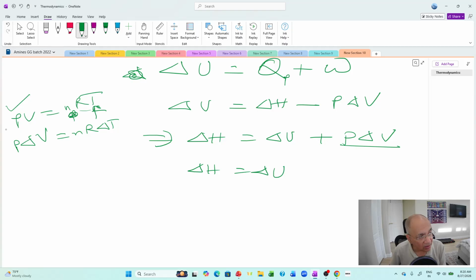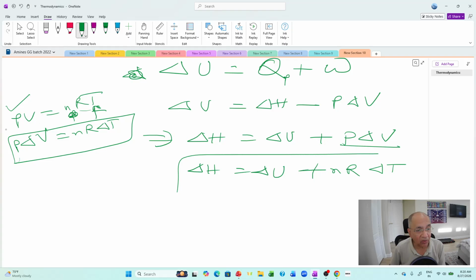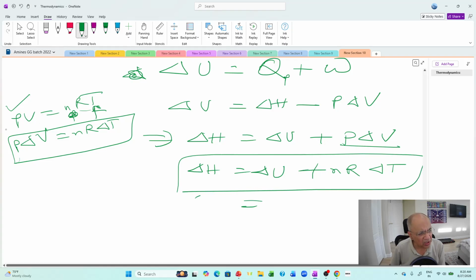In chemical reactions, temperature was constant, pressure was constant, so we write delta nRT. But in an isobaric process where mass is constant, n is constant, del V varies with del T. So in place of P del V, let us write nR delta T. That will give you del H, which is also equal to n Cp delta T. We will be solving problems.